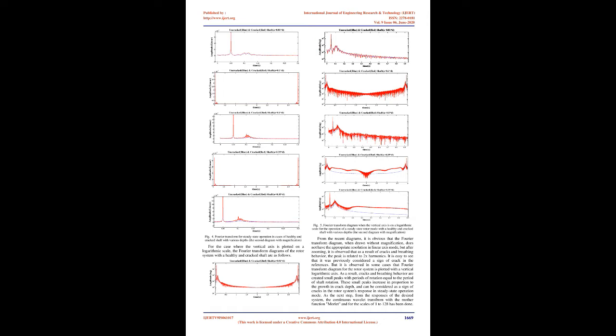Here, l is the length of each element of the shaft, which is the total length of the shaft divided by the number of elements, and EI is the bending stiffness of the shaft. For cracked elements, the flexibility matrix is extracted as equation 14. In the above matrix, F0 is defined in terms of R, the radius of the shaft, and ν, the Poisson's coefficient. Additional flexibility coefficients created by cracks are available in reference 15.